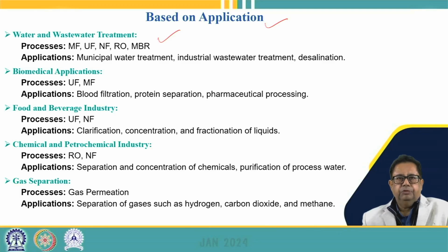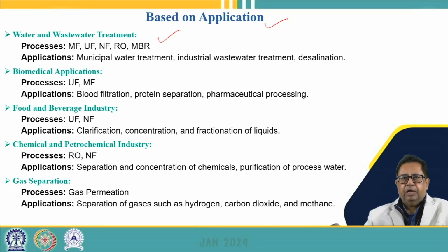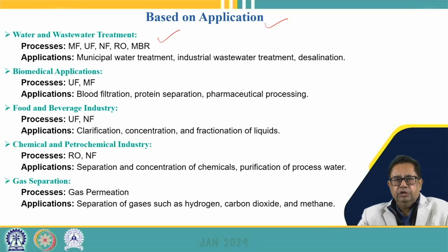Okay. So here, as we have already talked about the membrane bioreactor, the membrane bioreactor can be used for the treatment of the wastewater. Or we can talk about the anaerobic membrane bioreactor. It can enhance the sludge retention time to a very great extent. As we know, the hydraulic retention time and sludge retention time or the sludge age are different in the bioreactors. This means that when we apply a membrane process to it, it may hold the sludge for a longer time so that the sludge age or the sludge retention time increases many folds, and it has been found that the sludge retention time may go up to more than 100 days in such type of reactors.